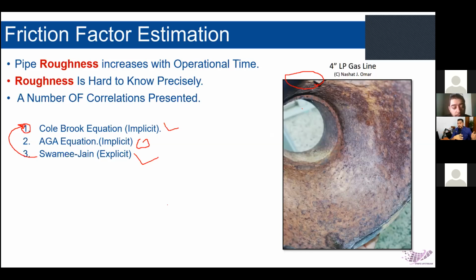Along with the wellhead pressure, you will get a flow rate from the pumping station. You will allocate these values. Now you have two points, which are the Q and the pressure. What you can calculate is the bottom hole pressure. So that was what I meant when I said they do not run bottom hole gauges for the injection wells. They do use injection logging tools, but this is not so often. They might do it every year or so in the best cases. So you have an injection rate, and from the reservoir or from the production wells you calculate, and you get more or less the pressure within the reservoir, correct?